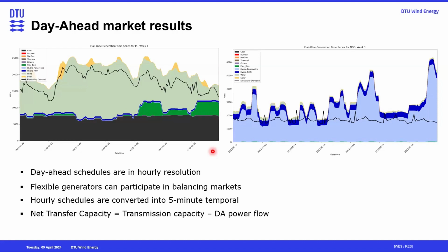We can see that both the countries are exporting countries, but the export of Norway is much more hydro driven, so that's much more dispatchable, and the export of Poland is much more dependent on renewables, and if there is high forecast error, instead of exporting, it will become importing for those hours.